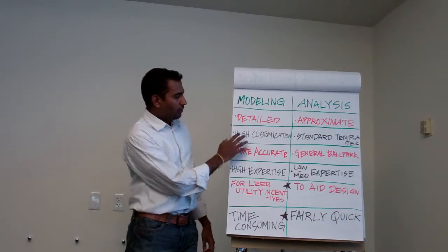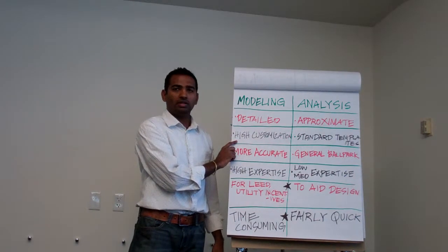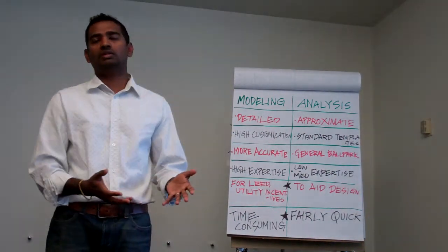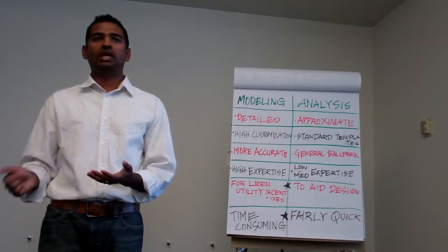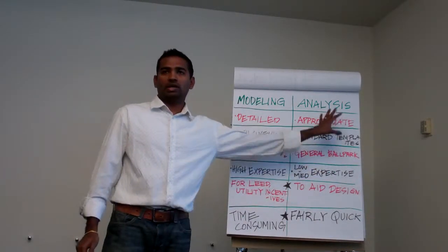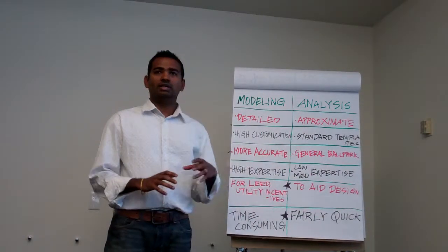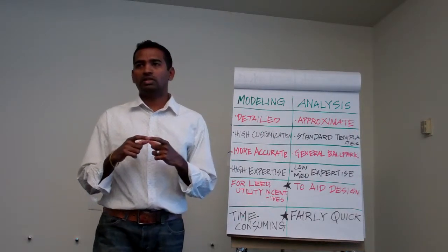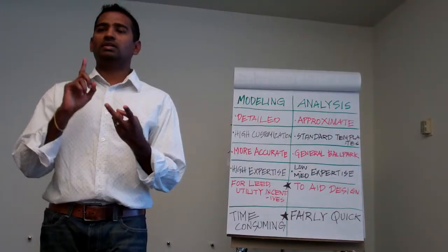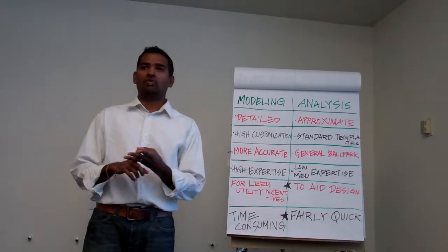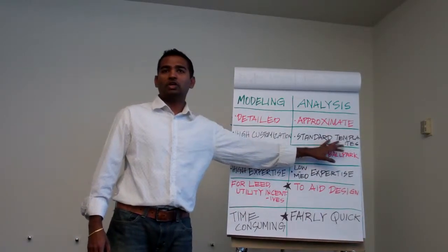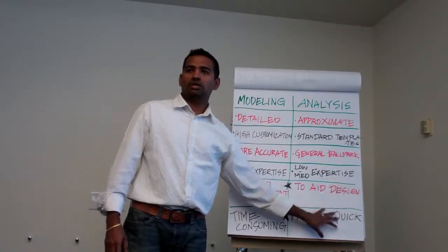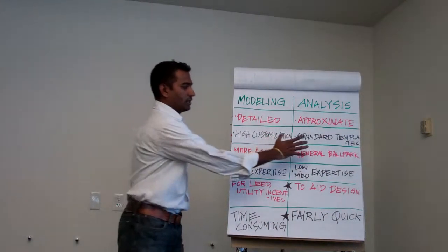So for energy modeling, there will be high levels of customization based on what the actual client wants. So you'll have to fine-tune your energy model to the nth extreme. So you don't want to do that on the energy analysis. You're going to use standard, let's say, a school building. What is the standard for a school building in terms of operations, in terms of number of people, how much hot water they use? You're going to use standards for that. It could be slightly different from what your actual condition is. But to avoid complexity, we want to stick with standard templates.